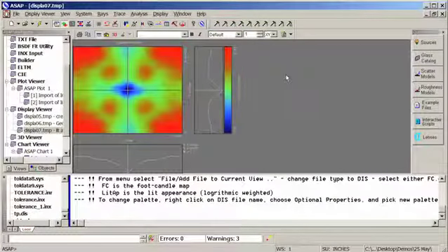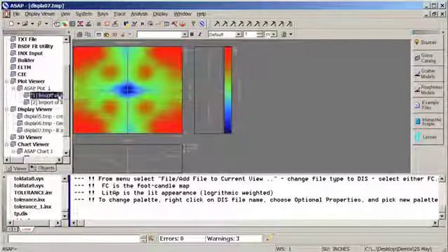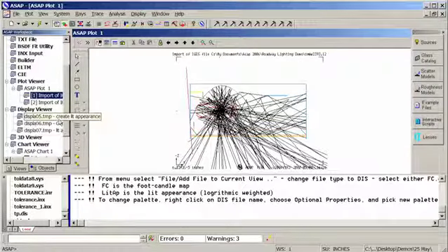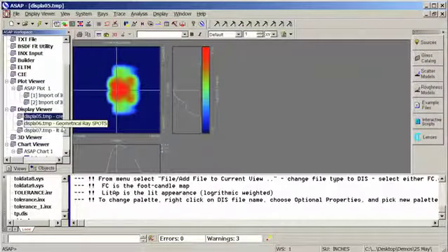Some of the analysis we can look at, not only is looking at the geometry and a visualization of the ray trace, but we can also look at lit appearance type data. And with the lit appearance information, we can look at it in a linear scale, or if it's going to be light visualized by the human eye, we might want to look using a logarithmic scale that more represents the ability of the human eye, so maybe a log scale of 2.3 to 2.5.